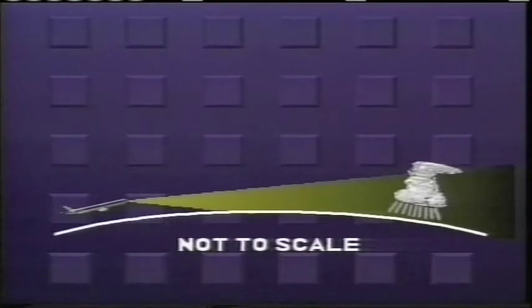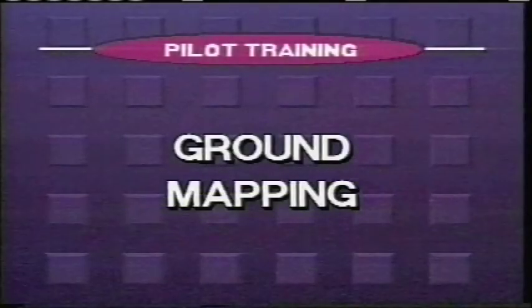If rainstorms are detected at long ranges, say over 100 miles, regardless of their displayed intensity, consider them significant storms and make course deviations as early as possible. Ground mapping refers to the process of using the Earth's surface as a radar target. The radar will ground map in either the weather mode or the map mode. The main difference between the two modes is the way the radar processes echoes.